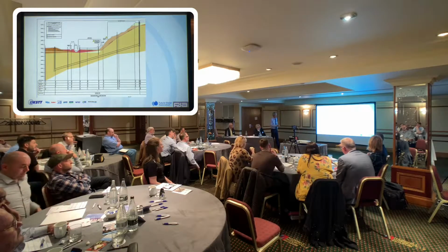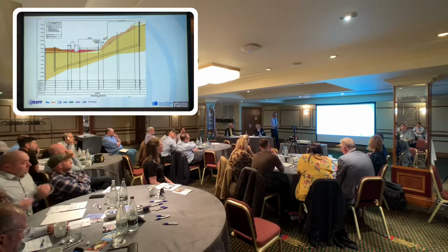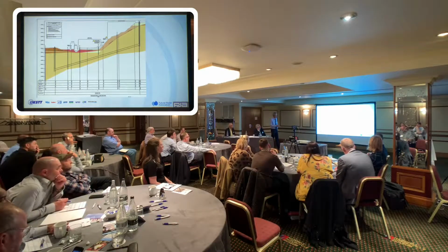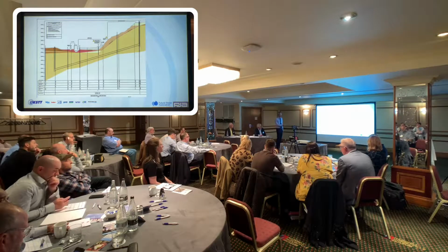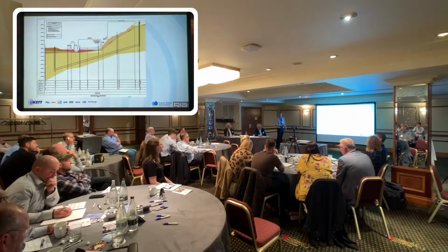One of the interesting things to see here is the change in the topography and how that impacts on cover to tunnel and the groundwater profile. So the groundwater roughly follows the hill. So the worst position for overpressurisation and loss of fluid is actually halfway up the drive where we've got minimal cover. And we had to be very careful how we drove that tunnel and controlled face pressures.